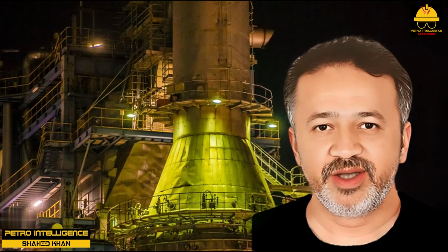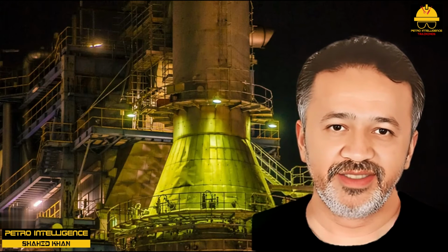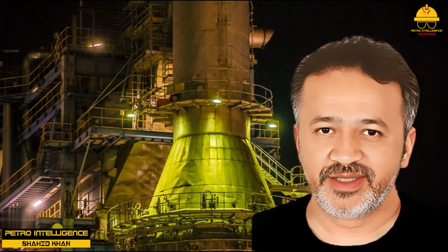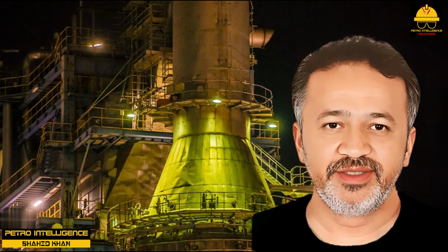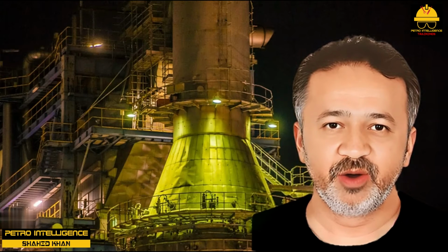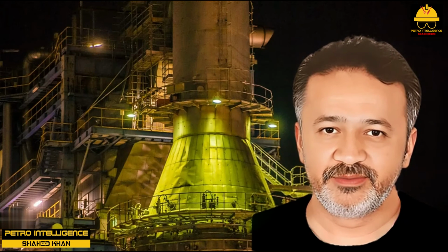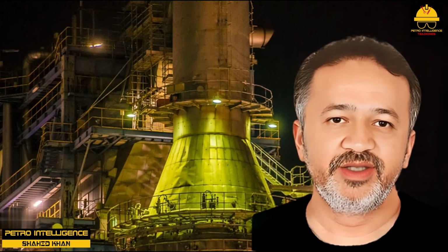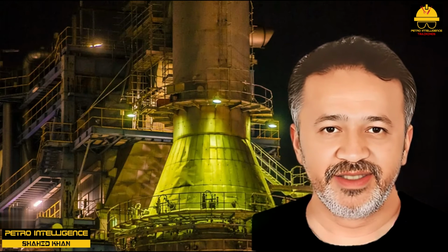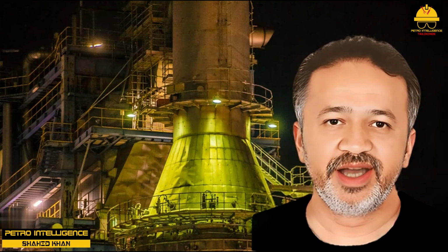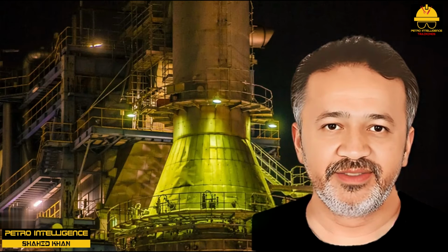Draft induced by wind. Running with a positive pressure below the bottom row of convective tubes is potentially dangerous, especially if there is an appreciable quantity of sulfur in the fuel. The sulfur dioxide would then blow out of the side ports and leak in the convective section. SO2 is a toxic gas.